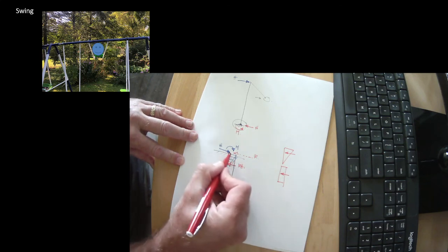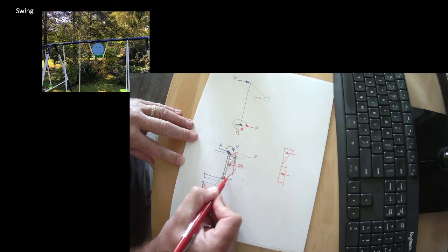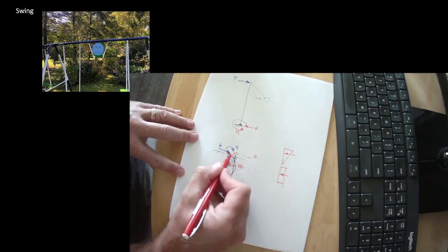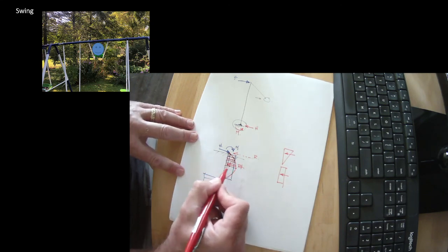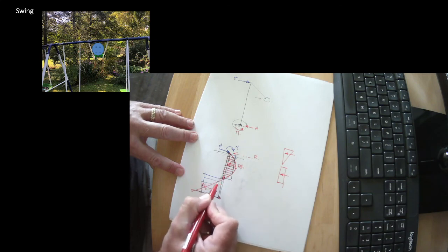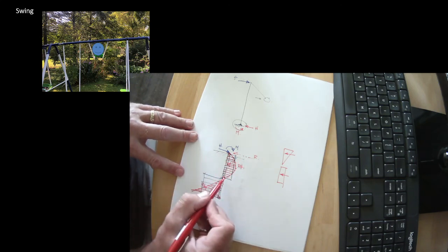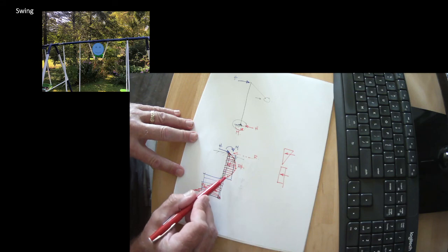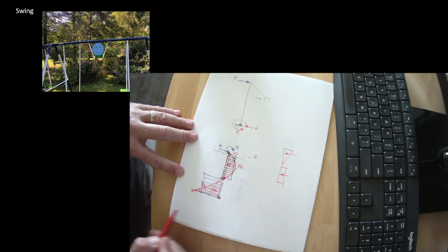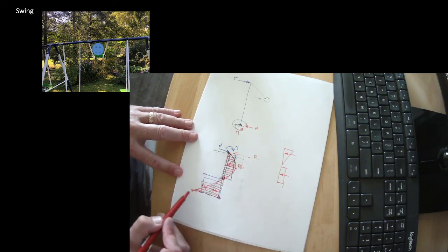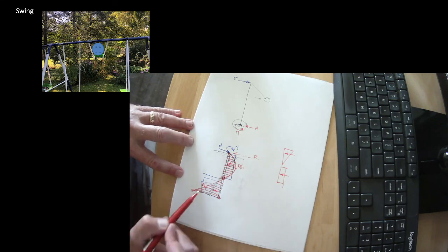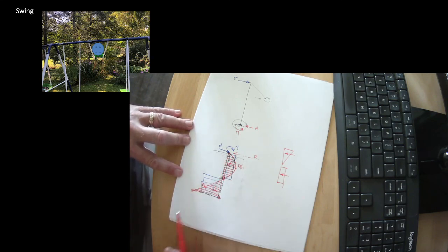So a guy named Cherniak proposed, what if it looked like this? What if that was our bearing pressure distribution? Satisfies all our constraints, right? It's 0 right at the top. It's 0 at the point of rotation. It's a maximum at the base. So this is our bearing pressure. This is the diagram that looks like our bearing pressure distribution for embedded pipe.